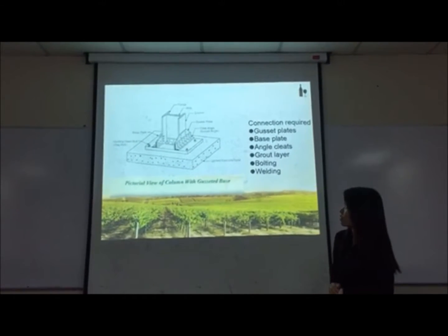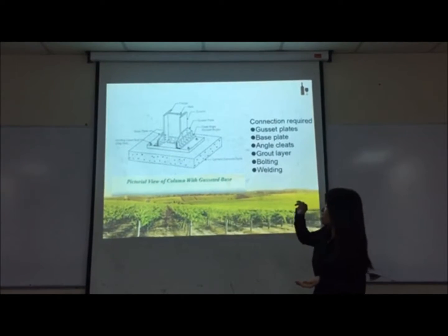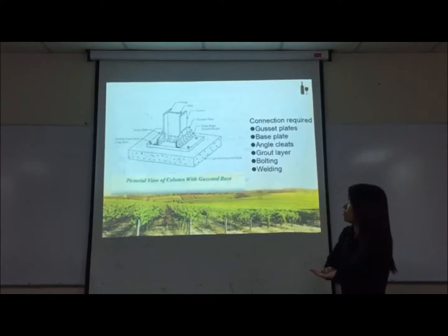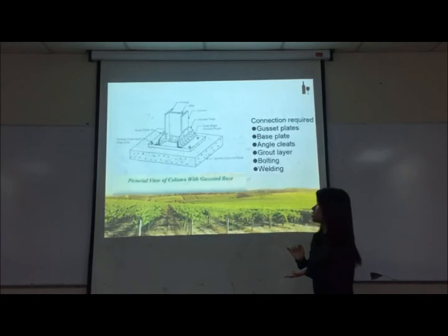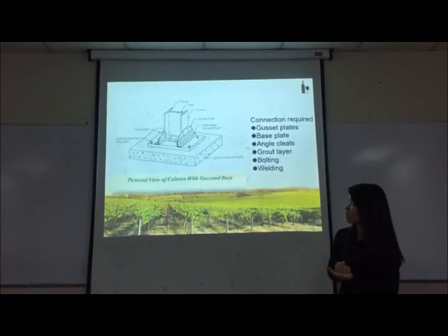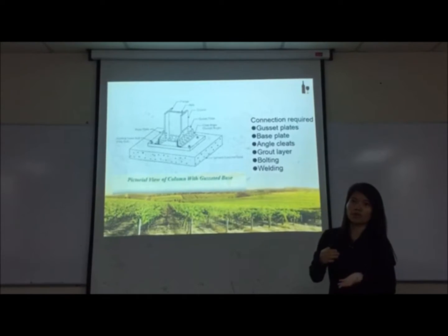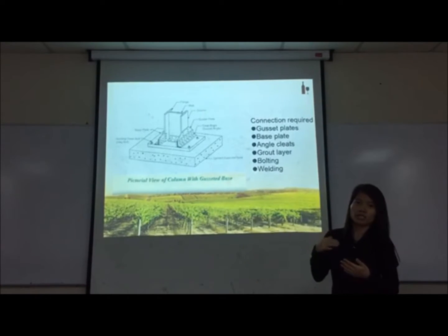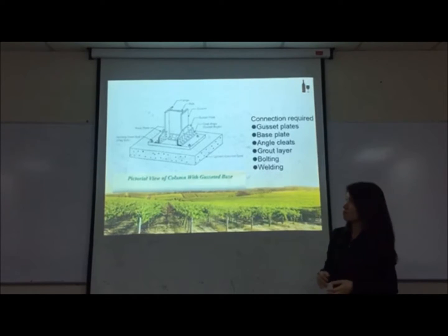For the bolting and welding, as the picture shows, the bolts will be bolted to the base plate and the angle plates to hold down together with the foundations. The welding will use fillet weld to provide extra strength to hold down the connections.